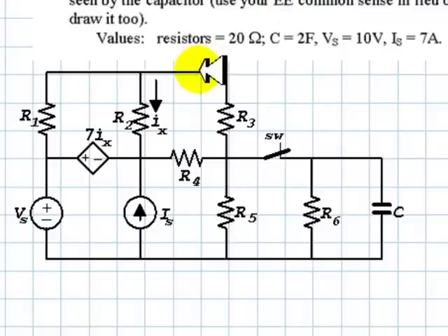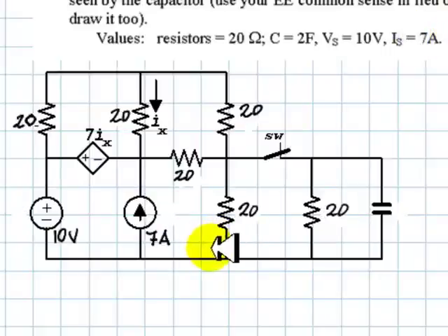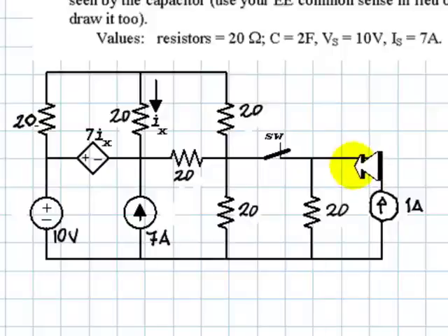The first thing I'll do is replace all those symbols with the numerical values provided. The observer of this circuit is going to be the capacitor, so the capacitor is the first thing I remove and replace with a 1 amp current source. What I need to compute is this voltage, V1A. I will use MNA, no surprise there.